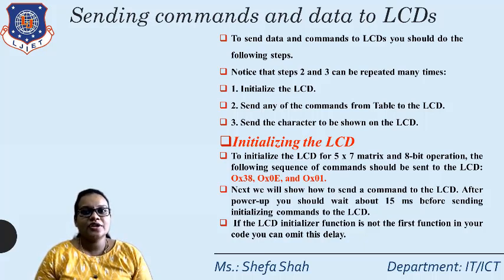And last, after the command is sent to the LCD, we can send the data. So the third point is to send the character to be shown on the LCD. Right. So step 2 and step 3 can be used repeatedly while using the commands onto the LCD screen. Right. So basically, first step, that is initializing the LCD.